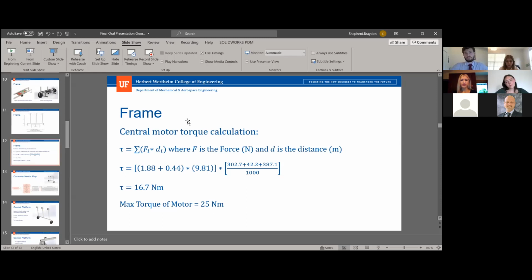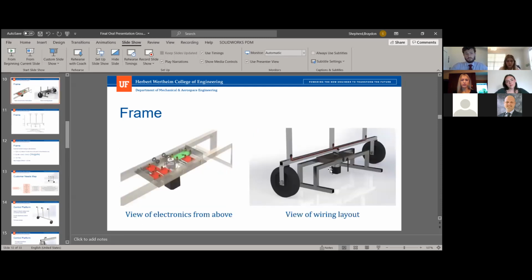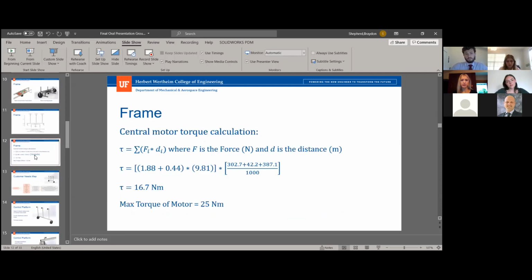Yeah, so this is the torque of the central motor. This motor is attached to the frame subsystem, the steel frame. This is our biggest motor, the one that has the biggest gear ratio, while the other ones are also the same motor with a smaller gearbox, but they attach to each individual reflection platform. That is actually one of the features that allow us to keep the losses under 30%, is that we can individually rotate every reflection surface instead of rotating the whole module at the same angle.